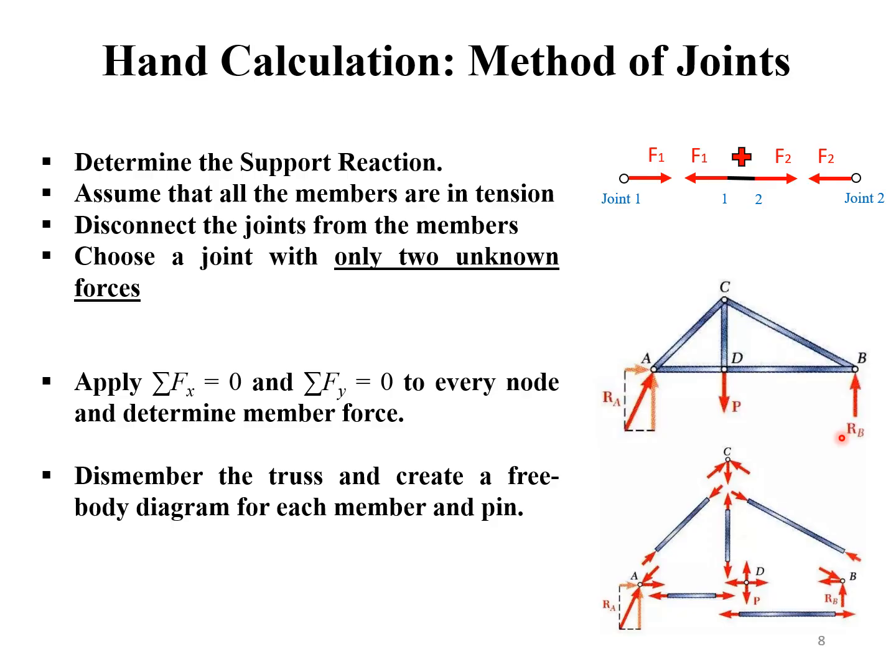Then we can draw a free body diagram for every single joint and work through them one by one to solve the unknown forces acting at each joint. We solve the unknown forces using the equilibrium equations. Since all of the joints are pinned connections, there are no moments, and we only need to consider equilibrium of the horizontal and the vertical forces.